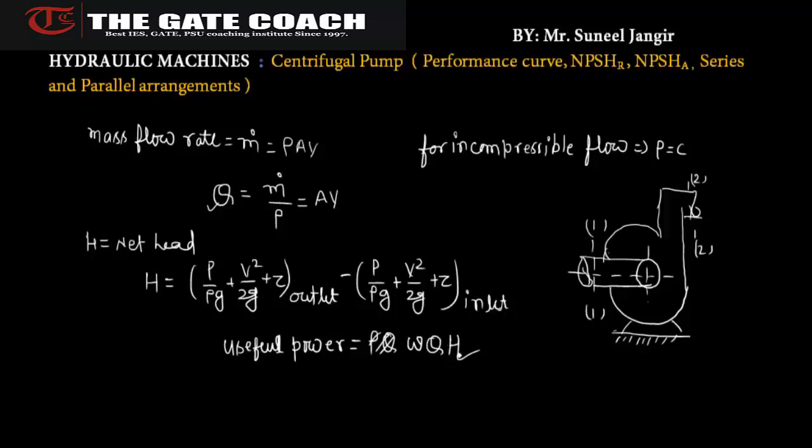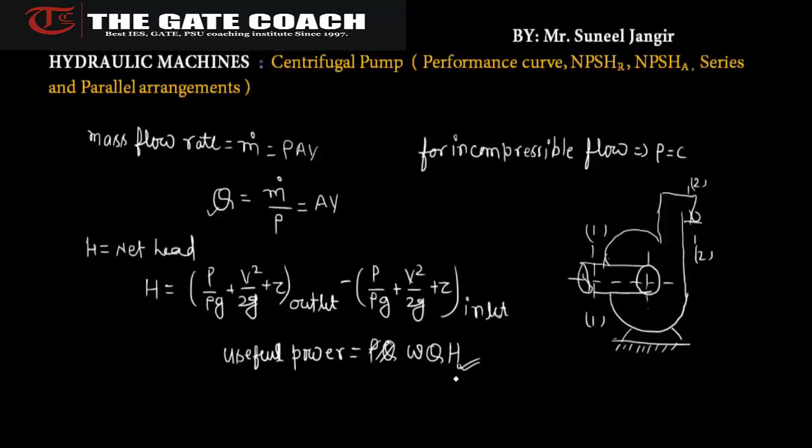So this net head is proportional to the useful power delivered to the fluid by the pump. You can see that this net head includes all the parameters.